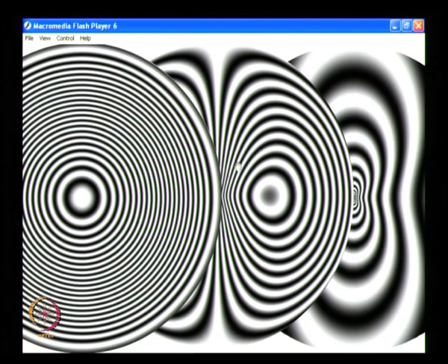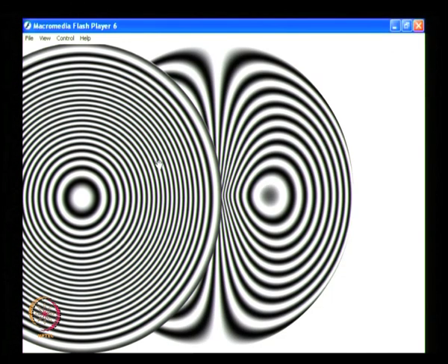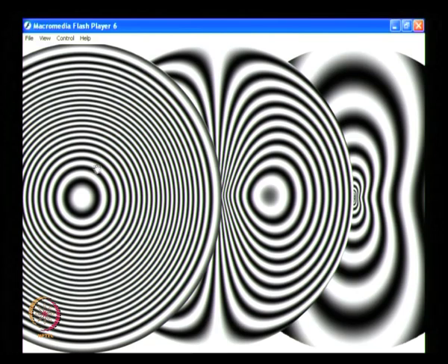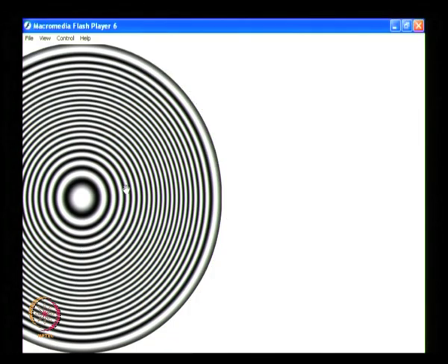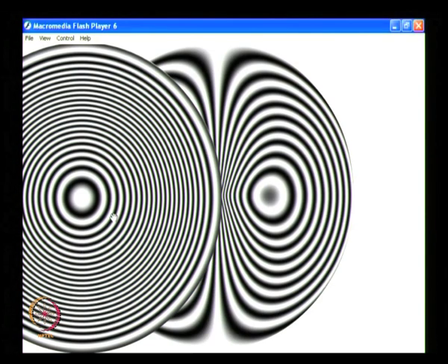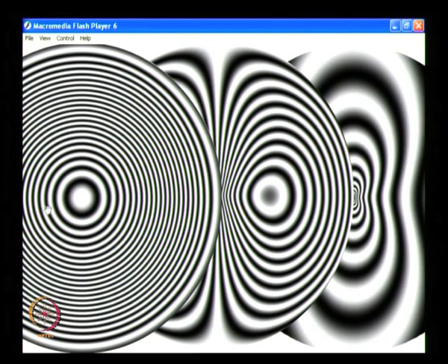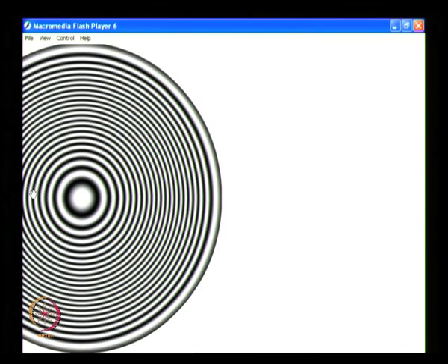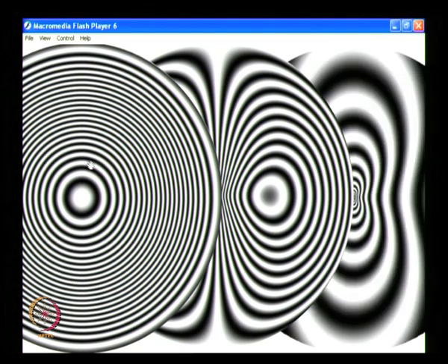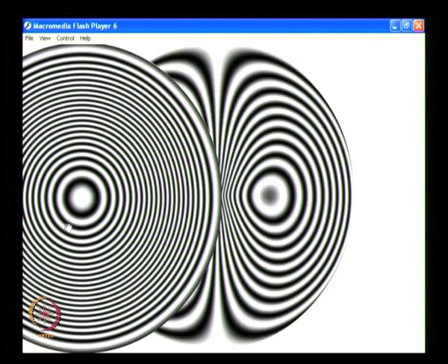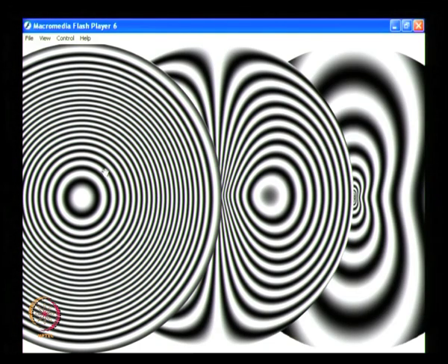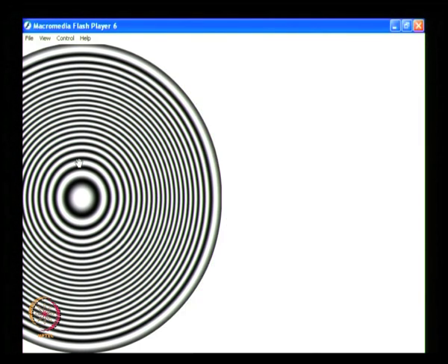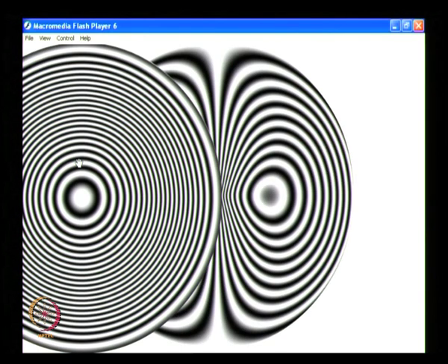Now, you know that this is the slope, this is the curvature information, and each of this requires separate optical arrangements, and you may be able to get this displacements by the technique of holography or speckle interferometry or shadow moire. What you see is the simulated fringe patterns, and when you really make an experiment, the fringe patterns will follow this closely, but the quality of the fringes depends on the technique that is being used.